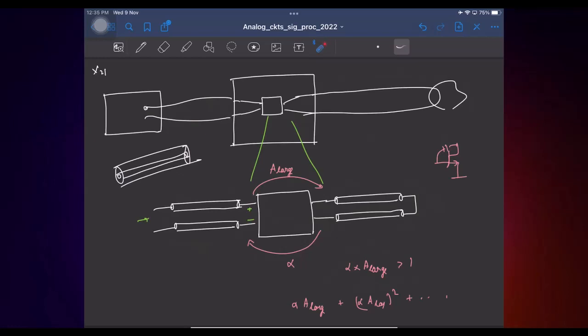right? Cool. So these are some of the practical difficulties in actually measuring these parameters, where you want to have short or open on one end of the port. Okay. So now, if you think about it, all these problems are arising because you have multiple reflections back and forth the line, right? It's not behaving like a short circuit because something goes and comes back, and that's what alters the impedance here. And similarly, this instability is happening because you have infinite reflections. Some signal goes, comes back, and then it keeps going.